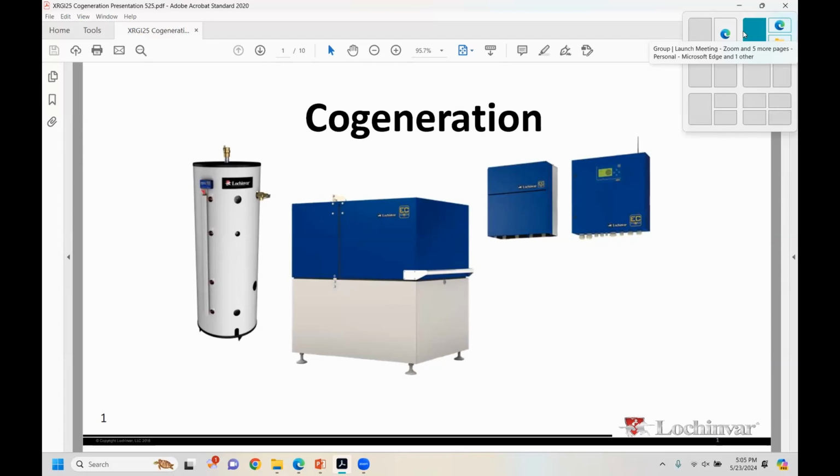So this is a micro cogen. It produces 24 kW, and it produces about 160,000 BTUs an hour. This is a product we picked up maybe in 2018 or so, George. I like to bring this up as an example because you go to a lot of these housing authorities, and I've installed these in many housing authorities around Massachusetts and Rhode Island, and you'll see 500, 600,000 BTU water heaters. You'll have two of them, and you'll have all of the storage.